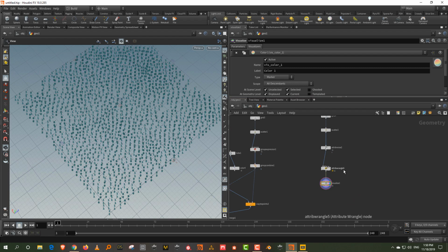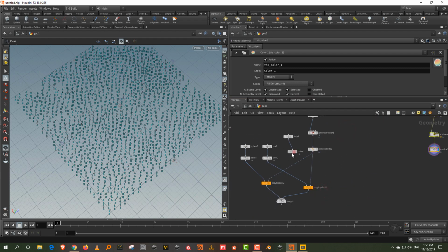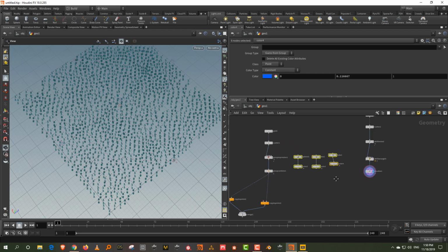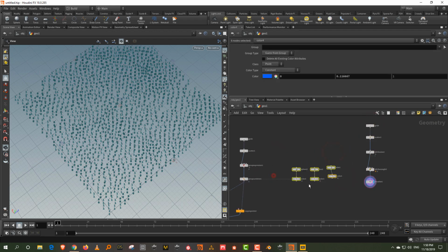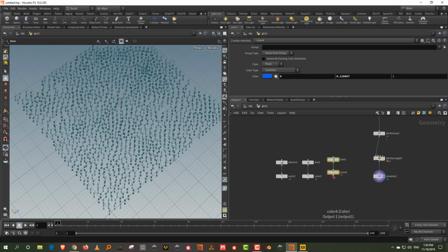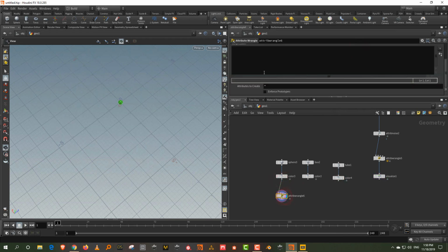Now let's use this. So what we do is we take our 3 objects. I'll just disconnect these guys, and you need to create the same attribute here. Keep them to a side and just create a wrangle, and we create i@variant is equal to 0. So let's say this is 0. So it's 0, 1 and 2, or any order that you want. Plug this in and then Control C, Control V and plug that in. So this will be 2 and this will be 1.